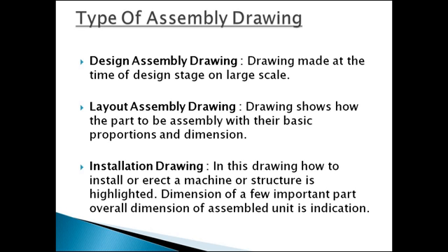The designer must understand the capacity of the machines present inside our company, and keep the geometric dimensioning and tolerancing as per our machine capacity, so that there will not be any problems at the time of manufacturing. Because if you keep tolerances that cannot be achieved on our machine, it becomes very difficult to manufacture inside.